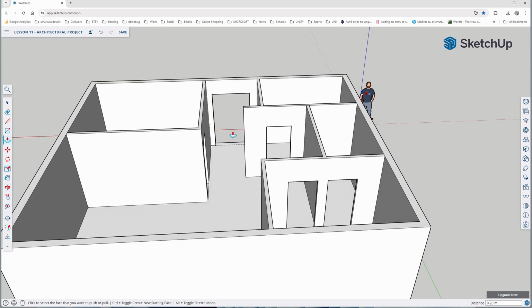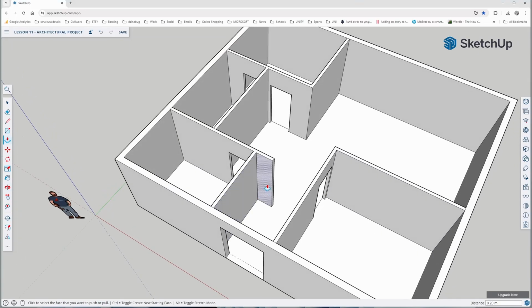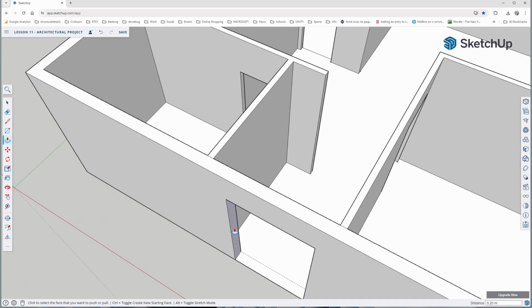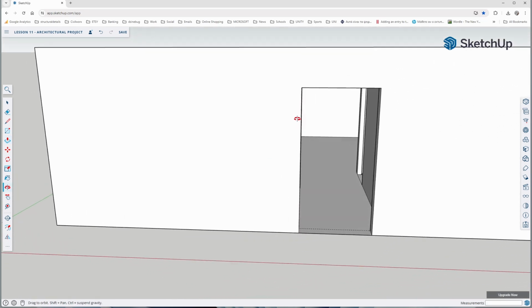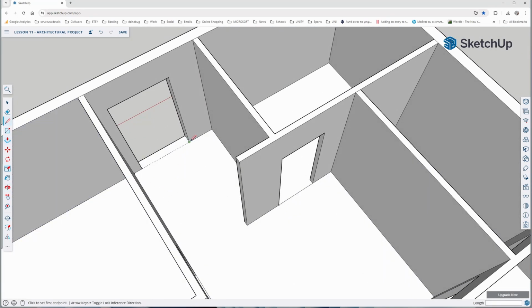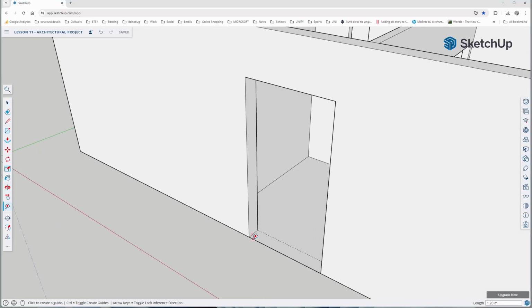I think we need to make our exterior door a little bit smaller in width, since if we're going to install a wardrobe here, we don't need our door to be interfering with the wardrobe. So I'm gonna pick up this wall and pull it for about 0.3. Let's check if this is okay now. I think it's not interfering. Let's draw a line just to make sure. From here, okay, it's exactly the same. So we made our exterior door to be a width of 1.2 meters.